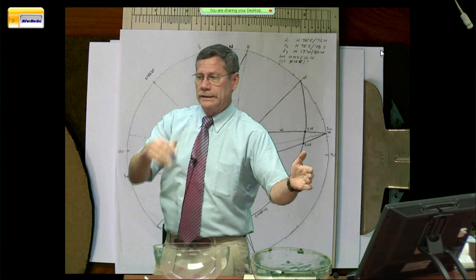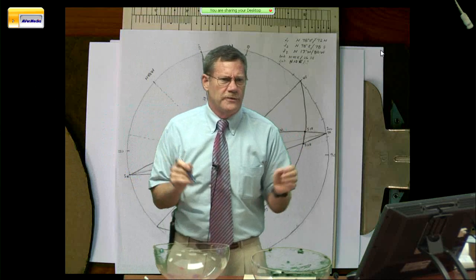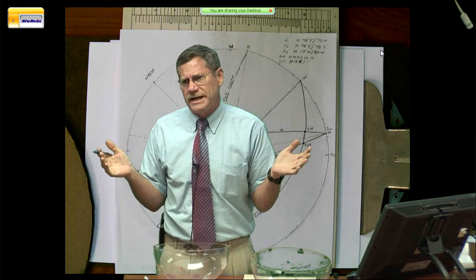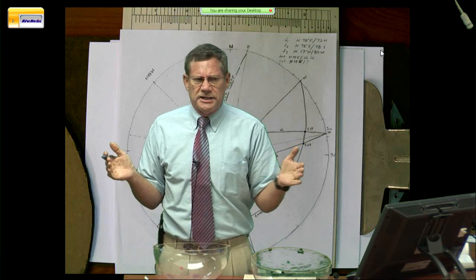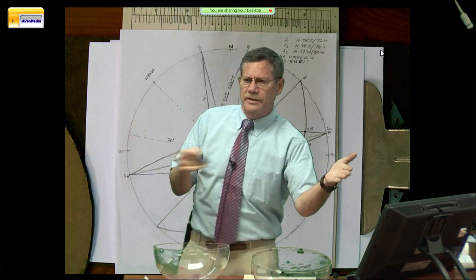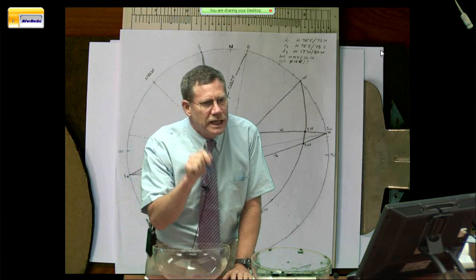Let's run that one. Here's the maximum value. Let's run that one. And we have a big word for that. It's called a parametric analysis or a feasibility analysis. What we're saying is, under extreme conditions, that joint could be dipping as low as this number, so that's the one I'm going to have to design with. I got to design for the weak link.